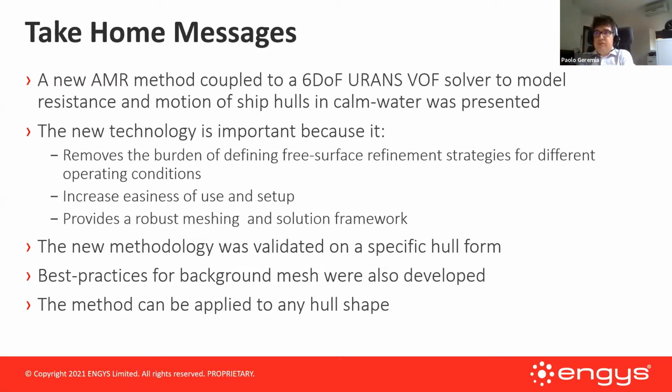The AMR technology is important because it removes the pain of defining a free surface refinement strategy, which is efficient for different operating conditions. So this makes the life of the engineer easier. It's easy to set up and to use because it can be automated in terms of scripting, and it provides a robust meshing and solution framework, which can be easily applied to different hull forms.